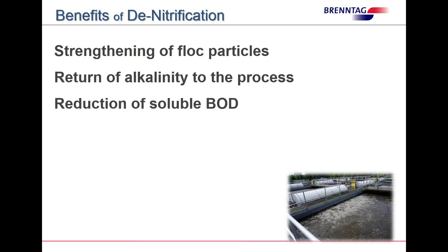You get a reduction of soluble BOD. Now, why would you do that? Because the bugs are still working in a 0 DO atmosphere. We're also getting rid of the nitrates because they're using those nitrates to get rid of the BOD. And I've seen when people have denitrification occurring, the soluble BOD will be very, very low coming off the effluent. If you normally would have a 5, 6, 7 BOD, you could get down to a 1 or a 2 if you're denitrifying on a normal basis.